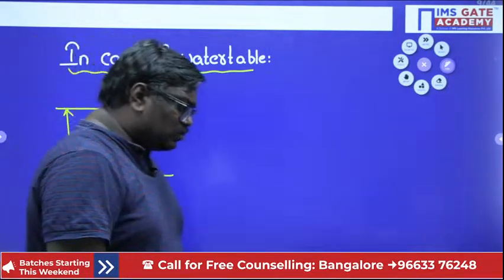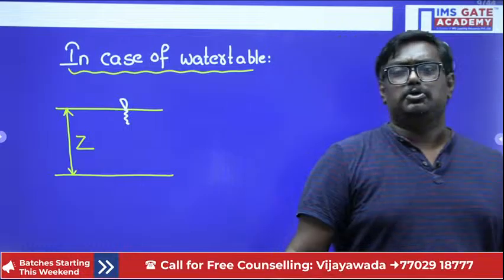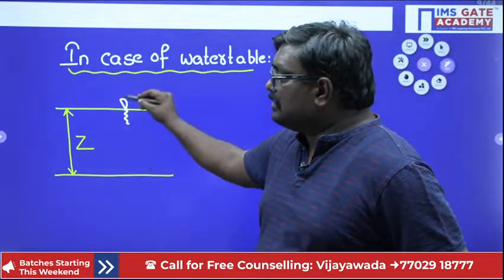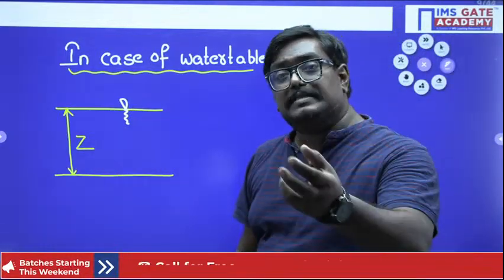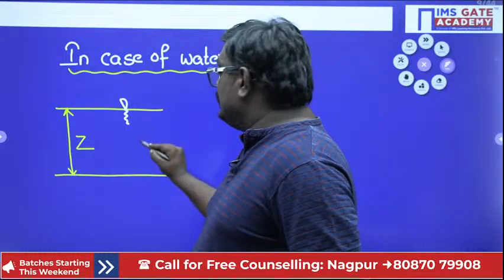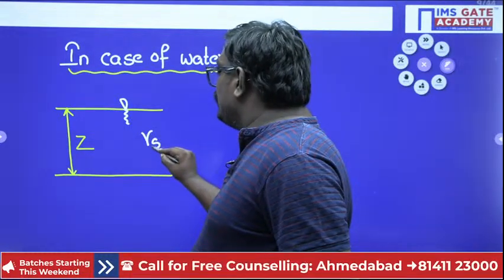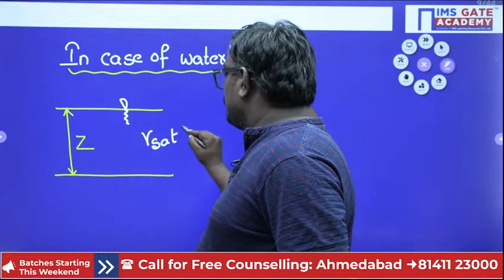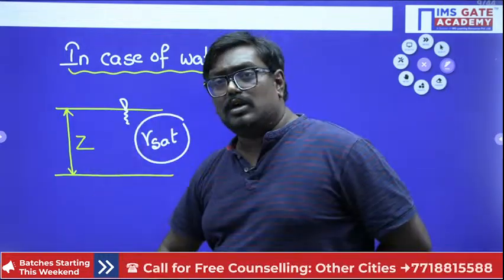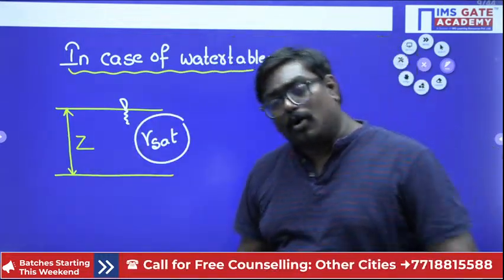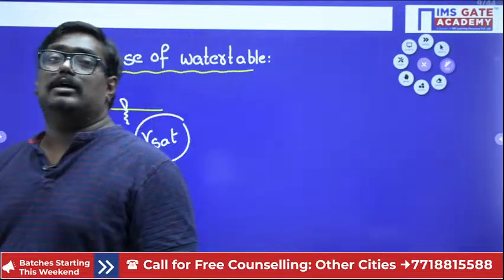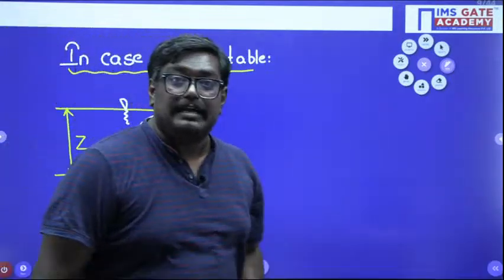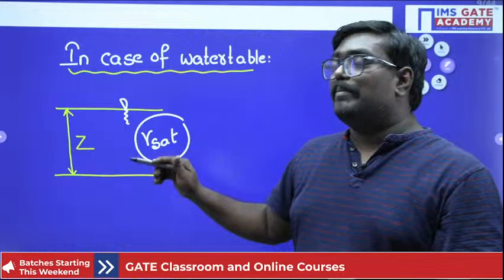Now, my dear students, you should understand that whenever there is a water table, the state of the soil will be saturated. What will be the condition of the soil? Because the voids are completely filled with water, the unit weight will be considered as gamma sat.